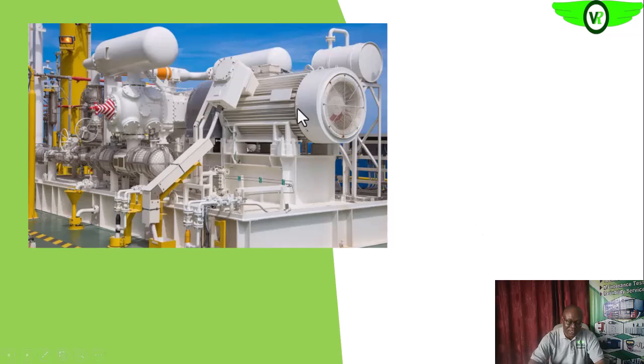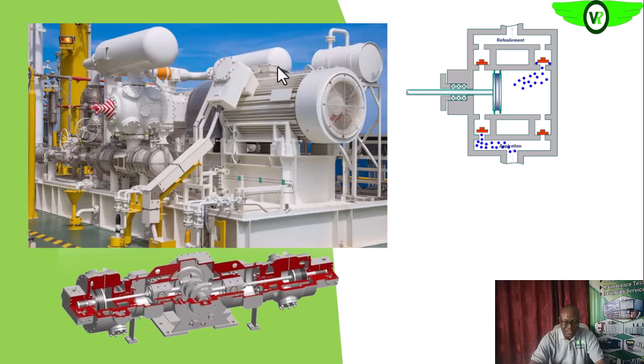This is an example of a reciprocating compressor in the field. This is the driver, and this is the one end of the compressor. We have the intake valve, which could be a plate valve, and the discharge valve. That is the discharge, then, since it is two stage, there's another stage here, and it is sent to the intercooler before it is sent to the second stage for further compression. We'll get to see all of this later. So this is a double acting reciprocating compressor.